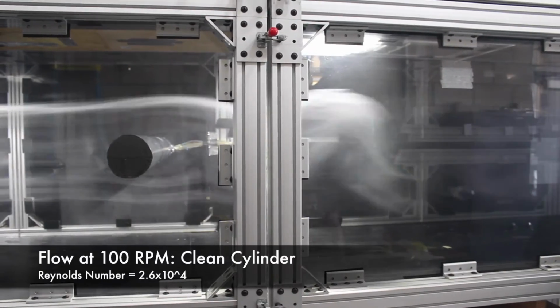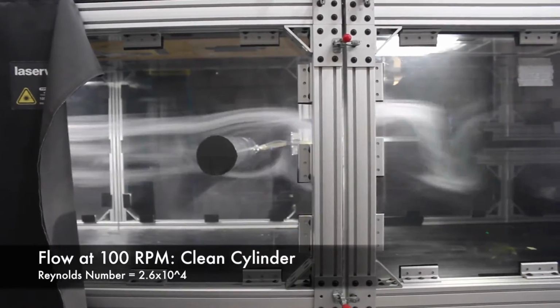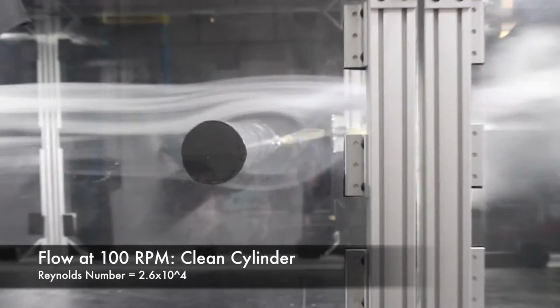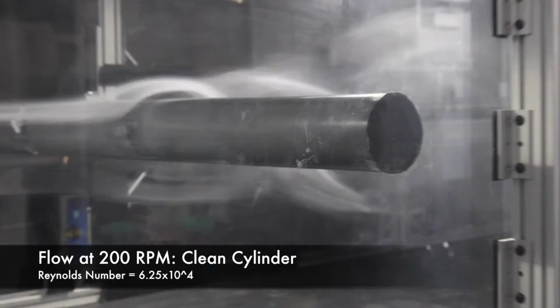The cylinder was visually inspected for any anomalies at the start of the experiment, and all 24 pressure ports were smoothed to the surface of the cylinder. A smoke machine was placed at the inlet of the wind tunnel to allow for visualization of the flow, and bright floodlights were positioned on top of the wind tunnel in order to make smoke more visible.